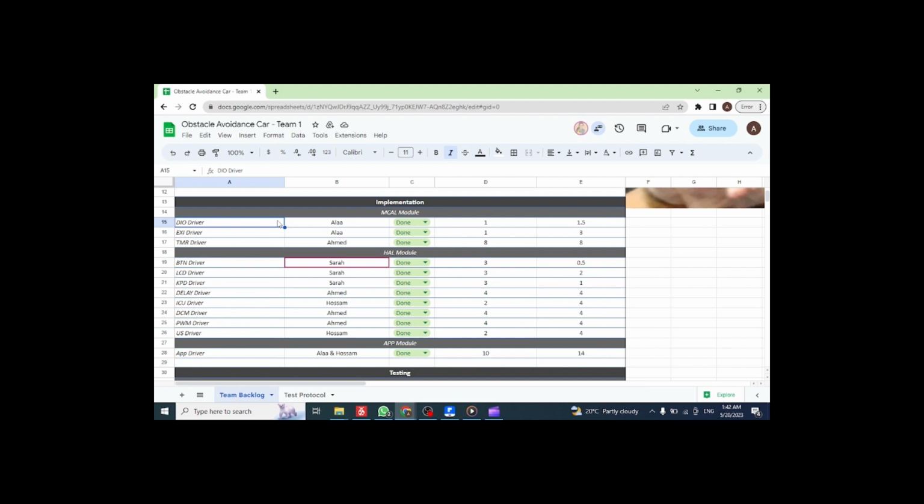As for the external interrupt, design and implementation did not take long. However, during testing, I encountered some bugs. Most notably, the external interrupt was firing unexpectedly, which turned out to be because the external interrupt could fire when the sense mode bit is changed, and was resolved by disabling the interrupt before changing the sense mode bit.